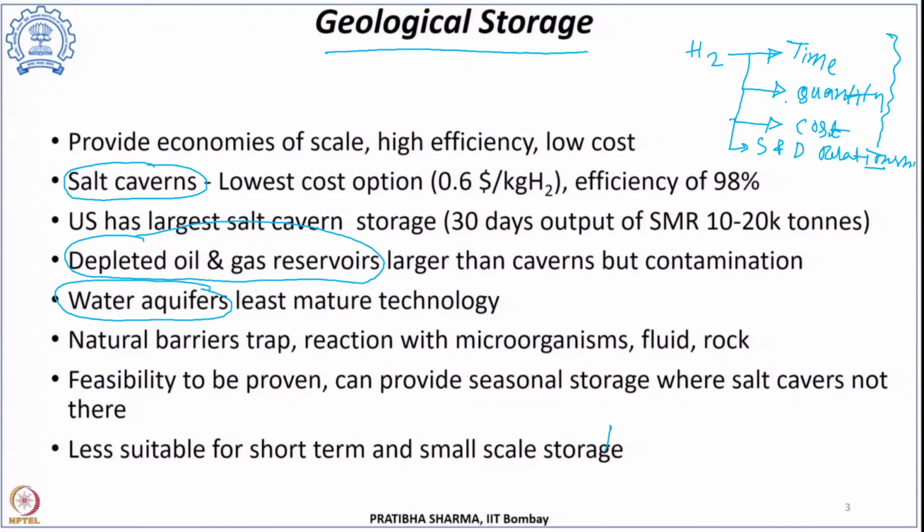Okay, so consider that you are storing tons of hydrogen, but you will not store it in a tank or a reservoir. You have to go for geological storage: salt cavern storage, depleted oil and gas reservoirs, this type of storage. Because if you make a larger amount of tank or higher tank sizes, the cost will be very high. Then you have to go for geological storage. So you have to think about how much time you want to store.